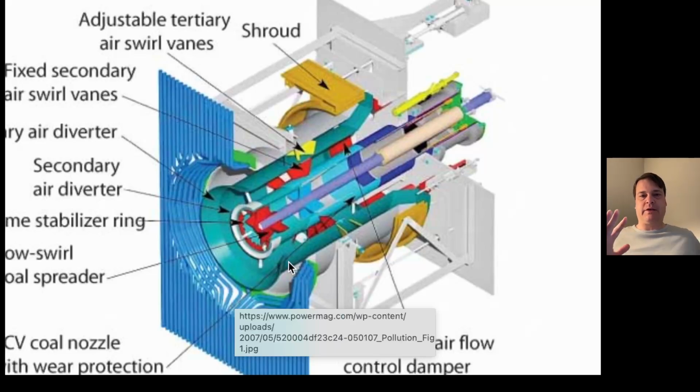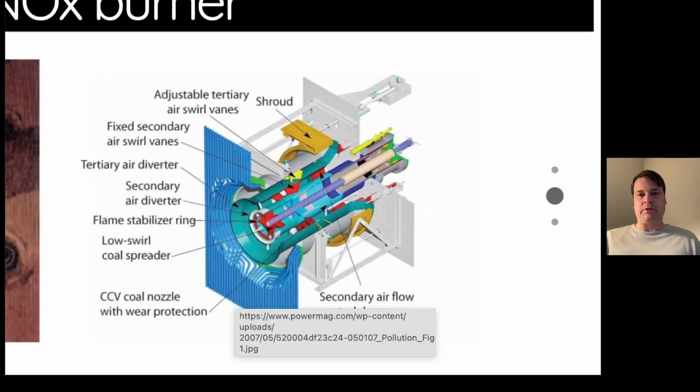It's kind of like a little divot almost in the wall and also in the burner. And that helps shape the flame and also provides a zone that can be heated that can radiate back to the gases at the coal to try to stabilize that flame a little bit. So there's a whole science behind just the design and use of these burners.